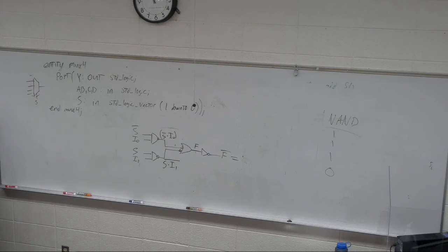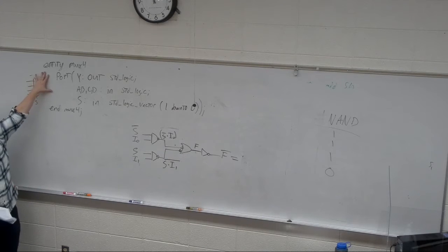If you're ever working in Vivado and you see an error that pops up that says error, black box, something, something, the black box is because you created an entity and then didn't define what was going on inside somewhere. So the term we use is black box. To the outside world, this is a black box. Vivado doesn't like that. It wants to have it specified somewhere, right? Because in order to synthesize it, it needs to know what it is somewhere. Okay, entity.